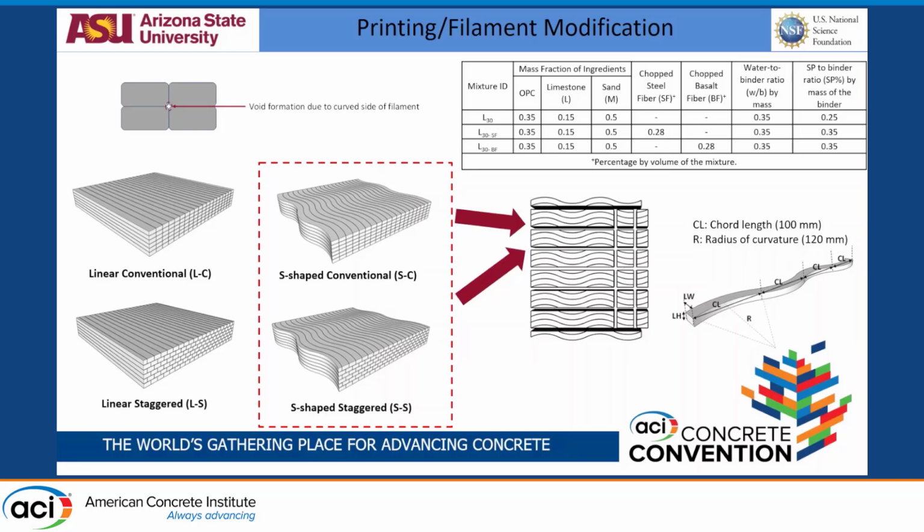And we believe it's not just because of the formation of interface, it's the alignment of interface we have in the printed system, such that the layer will be in a single continuous line, while the interfilament joints also will be in single continuous lines. So what we try to do is, how can we remove this? How can we make sure that they are not aligned?